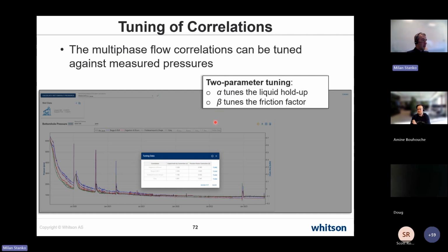Better, I think, before doing any tuning, is to see how the different correlations spread. You have 4 of them, and see what your gauge value is, and how close they are. It might not be a perfect match, but if it's within 15-20%, I will consider myself quite happy with that match.